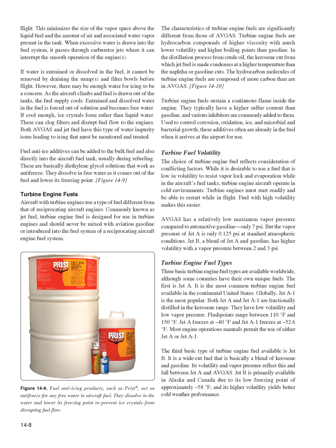Turbine fuel volatility. The choice of turbine engine fuel reflects consideration of conflicting factors. While it is desirable to use a fuel that is low in volatility to resist vapor lock and evaporation while in the aircraft's fuel tanks, turbine engine aircraft operate in cold environments. Turbine engines must start readily and be able to restart while in flight. Fuel with high volatility makes this easier.